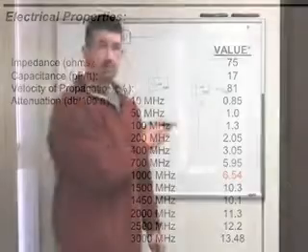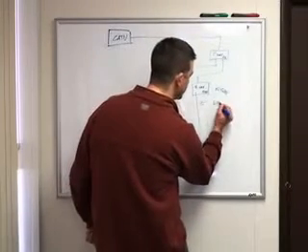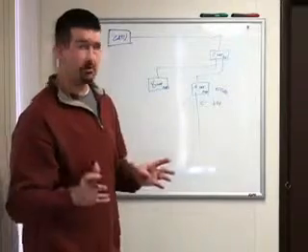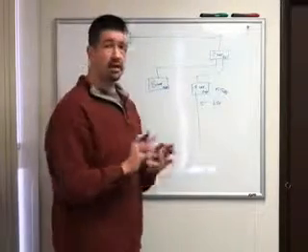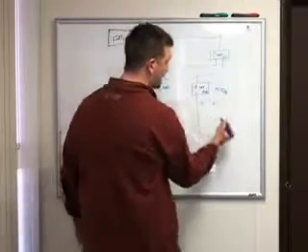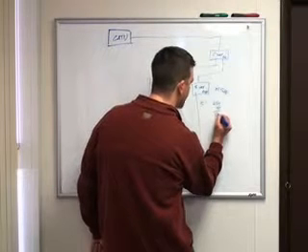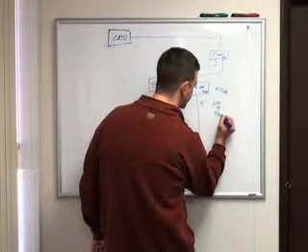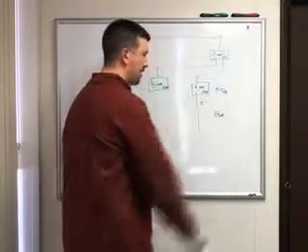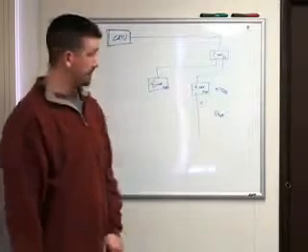In this case, the cable that we're using has 6.54 dB loss at 1,000 megahertz over 100 feet. So to calculate 75 feet, we're just going to multiply 6.54 times 0.75, which gives us 4.91. And that right there, our loss over 75 feet, would be 4.91 dB.